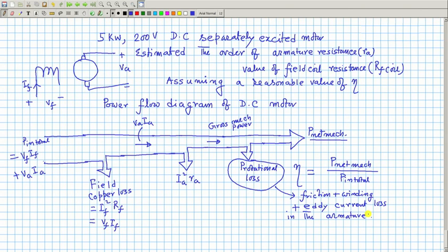See, in the case of a DC machine, all currents are DC, and that is why the field poles and the yoke structure are made of solid iron. Generally in small machines it is just a solid structure. This is the yoke, these are the poles, this is the stator part, made of solid iron, and here is the armature.